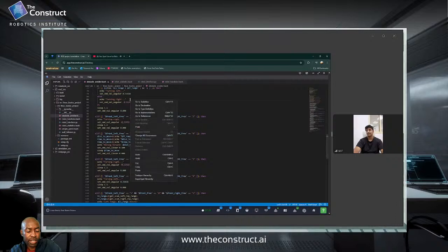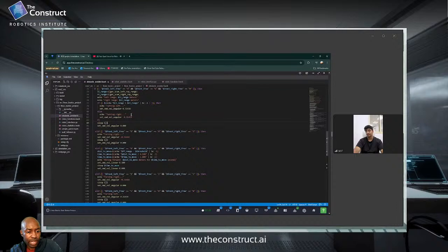Right, that's what I'm saying. You are setting the angular velocity because the definition of your command says set command vel angular, right? So yes, you are specifying the speed of rotation to be 180 degrees per, let's say, per second, or per whatever time unit you're using. Yeah, so it's 1.5 seconds over here. Okay, so that is the amount of time it has to rotate at that speed. Oh, okay, all right. Fair.